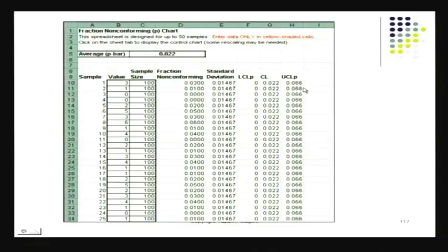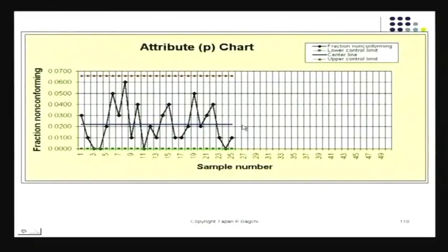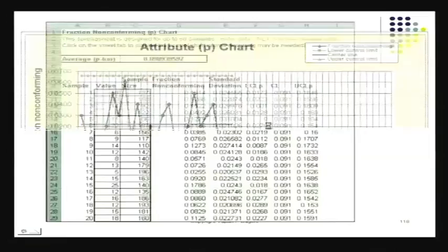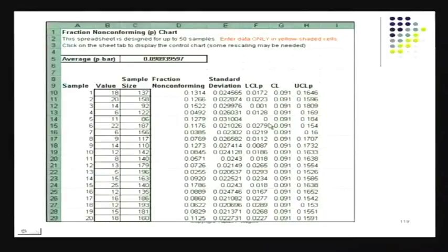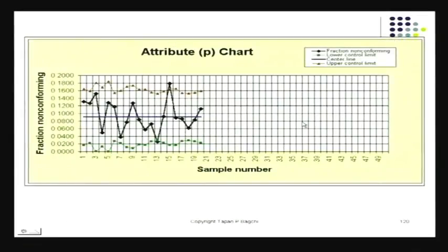Once I have my control limits, I have my regular reading there. I can do my comparison quite easily. Once I do that, I can construct my P chart without any trouble at all. P chart also can come out of the Excel thing. I can again focus on troubleshooting. That I'm able to do. So P chart would really be no sweat at all if you did it this way. And this is also not very difficult at all.